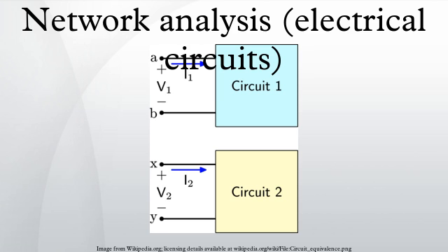It can be seen that the diode current rapidly diminishes to IO as the voltage falls. This current, for most purposes, is so small it can be ignored. With increasing voltage, the current increases exponentially. The diode is modeled as an open circuit up to the knee of the exponential curve, then past this point is a resistor equal to the bulk resistance of the semiconducting material.